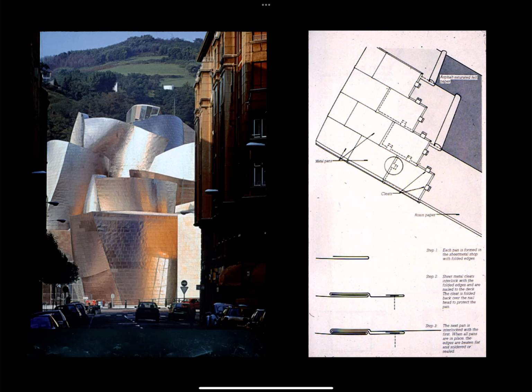And the innovation here is that Gehry caused a sensation by using titanium cladding. So this was the first building of any significance that used titanium cladding. Titanium typically isn't used because it's much more expensive than stainless steel, but there was a blip in the market at the time, and it became less expensive than stainless steel, and so he used it. Here, the titanium is extremely thin, much thinner than aluminum foil, for example, and it requires a continuous supporting backup layer.